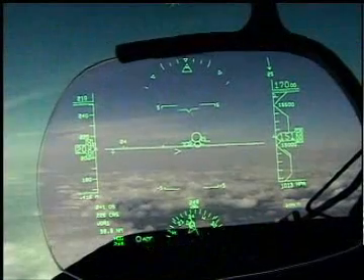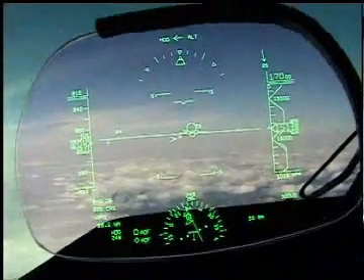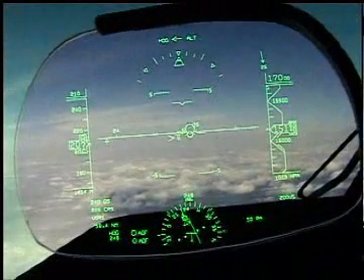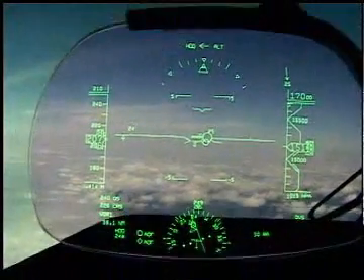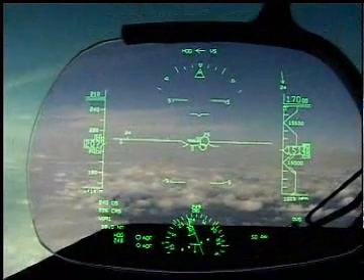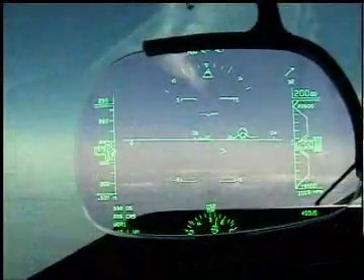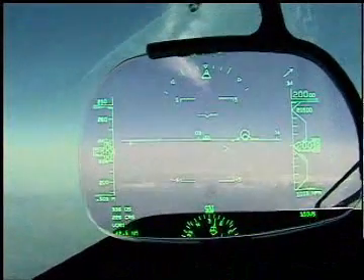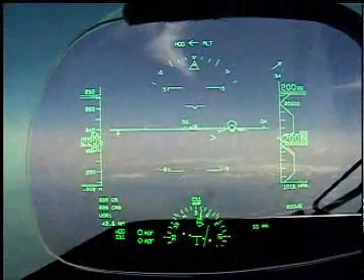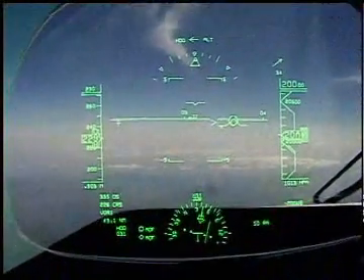Primary mode, en route level flight. This is a typical HGS display with the aircraft in straight and level flight with no acceleration. Holding the center of the flight path symbol level on the horizon and the flight path acceleration symbol on the flight path wing will accomplish this. In this illustration, the aircraft is level at the altitude and speed shown. Ground speed is a result of the headwind indicated by the wind arrow.